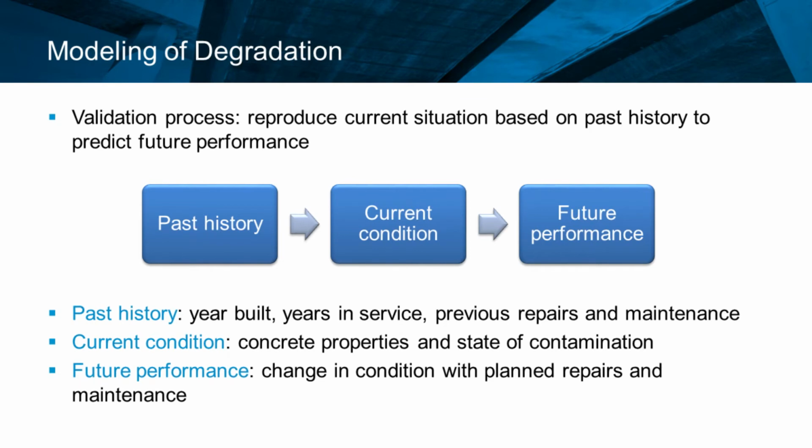I was talking about the current condition earlier. So this is the most important thing. At least when we do a repair of a structure, or we design a structure and we can use information from sister or parent structures, we need to know the current condition. So in that case, I think the least we can do is determine the depth of chloride contamination if we repair for chloride-induced corrosion, or if we have ASR, for example, we need to determine the depth because ASR creates subparallel cracking.